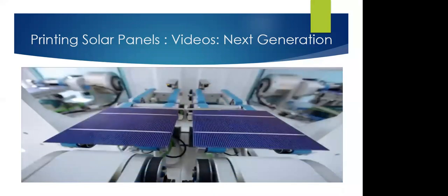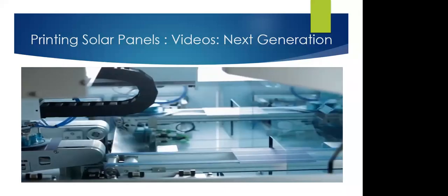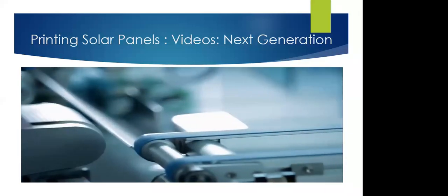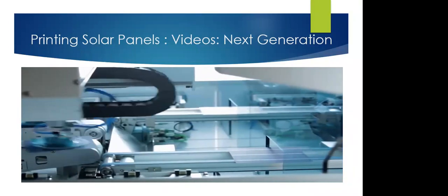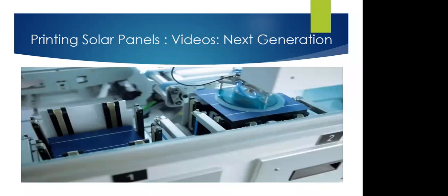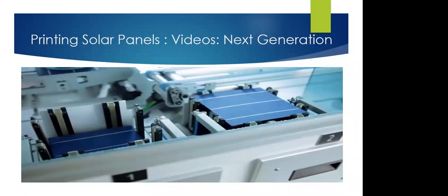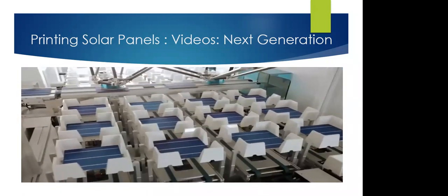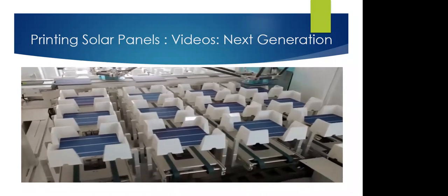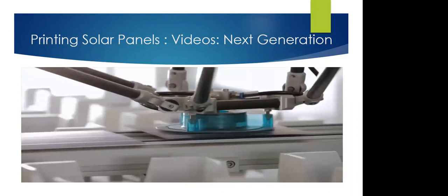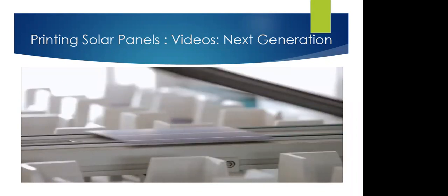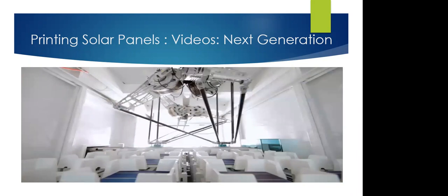The electronics industry commonly uses screen printing, feeding a paste through perforated screens, but the layers in printed circuit boards are hundreds of times thicker than those of PV devices, and turning materials into viscous paste alters their physical and electrical properties. Other techniques for printing PV devices have been demonstrated in the lab over areas of around 10 square centimeters. These include inkjet, slot die printing, spray coating the substrate, passing the substrate over a rotating cylinder, and moving a blade over the substrate to ensure a consistent supply.